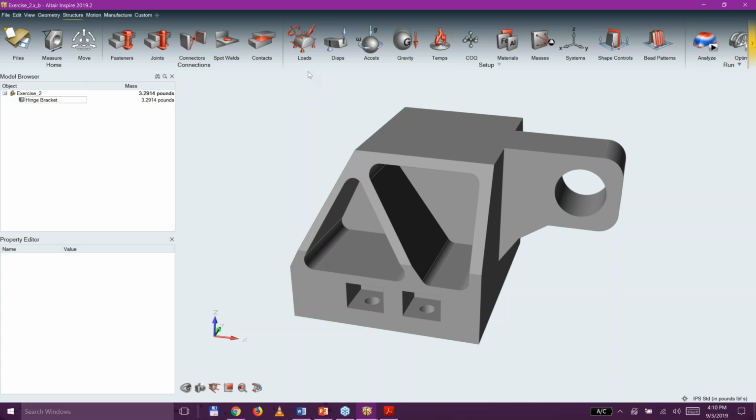So now, no longer is it just click an icon for a function. The icon itself describes what the functions are, and where you pick on that icon determines what function you're going to do. So these are all of our loads. Our supports are our constraints, our point loads, our area pressures, our moments, torques. So where you pick on here determines what you're going to get. So I'm going to come down here to my supports. I'll click on that. And this is how I can define supports for my model.